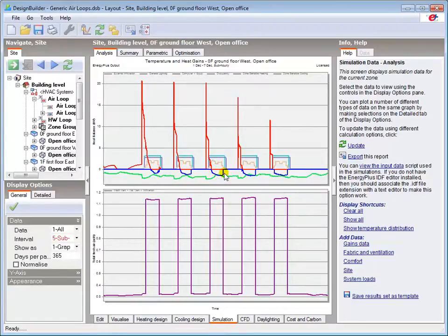This is the cooling effect of introducing ventilation air at a lower temperature from our AHU. Whilst the zone has a heating load, the ventilation air at 18 degrees C is helping to meet that load. But once the heating load is satisfied and the ventilation air is cooler than the zone air, the ventilation system provides limited zone sensible cooling.